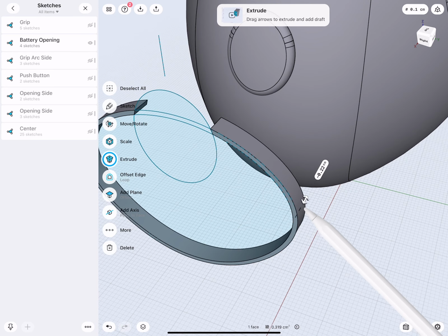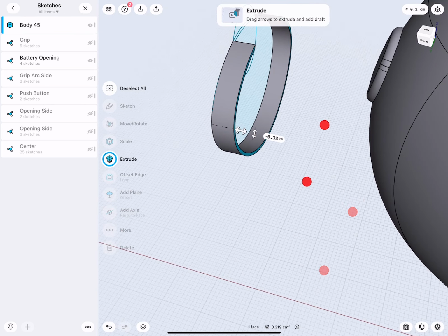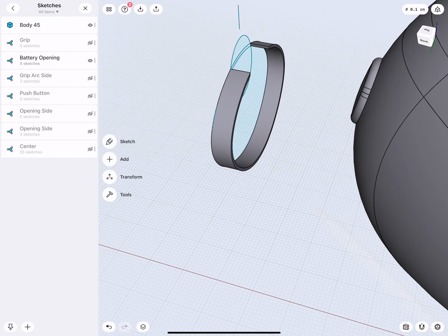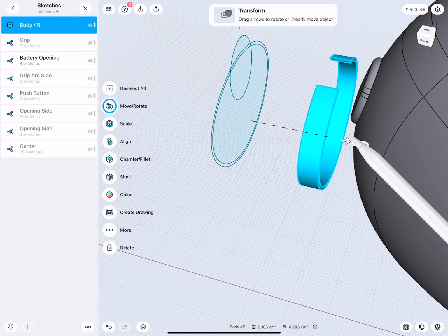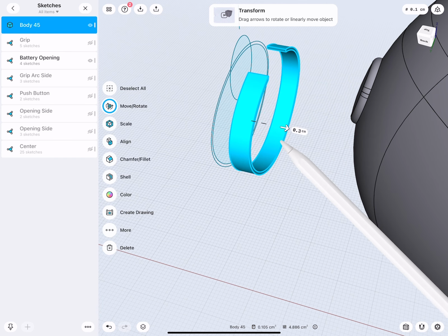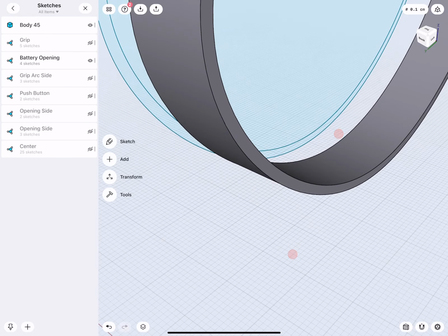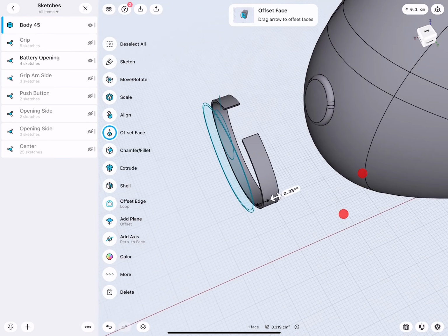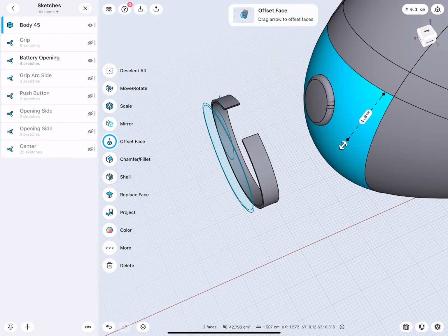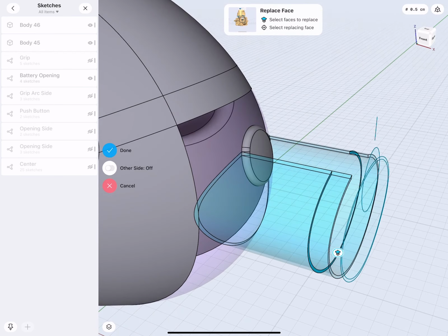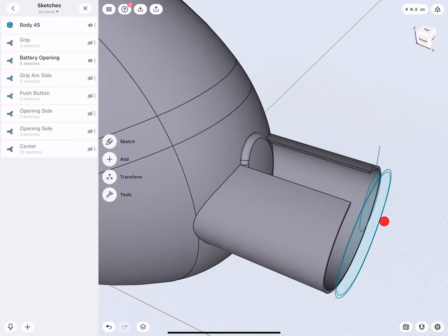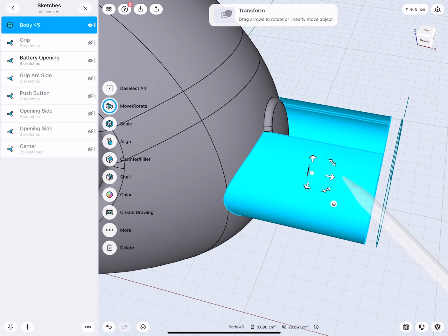It's actually easy. And another great example of the amazing capability of Shaper and direct modeling. So this surface I want to cut in there, but you can see that this is flat and this is curved. I need to fold this surface over this surface. And that's actually the replace face command. There, you see now how this got moved. Done.